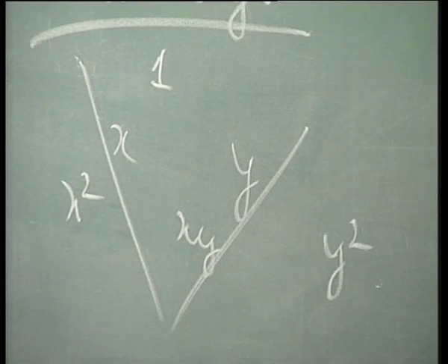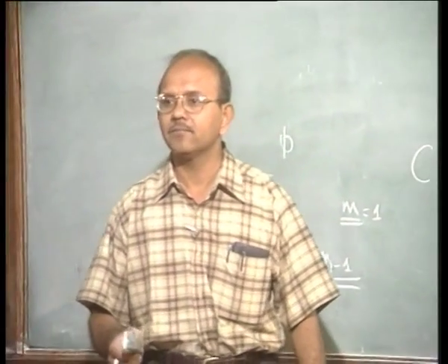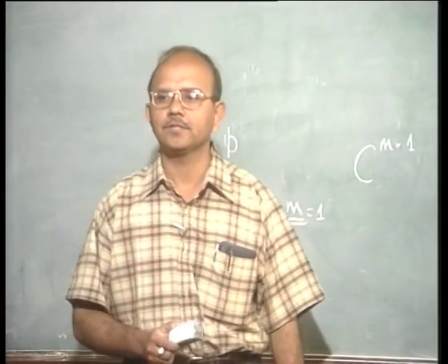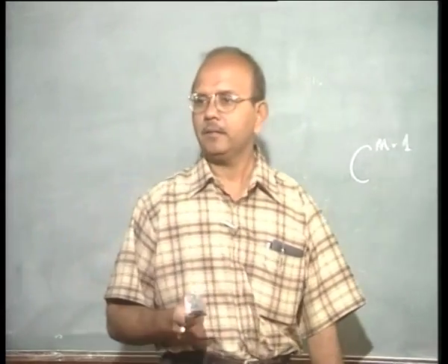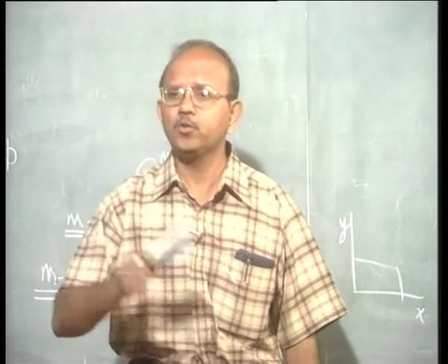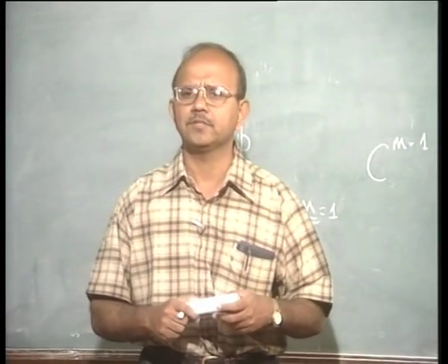Okay, for example, we did this for a rectangular element. Then what did we do? We then swapped a0, a1, a2, a3 for u1, u2, u3, u4 or v1, v2, v3, v4. In that process, we got what are called shape functions. Is it clear? Now the question is, should I do that every time? Yes, you can do it every time and get the shape functions.